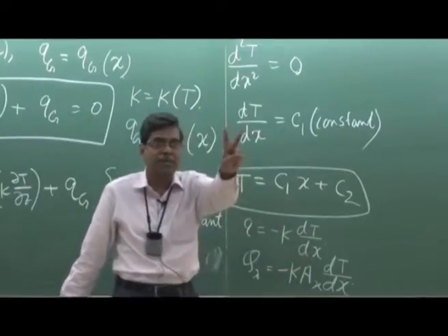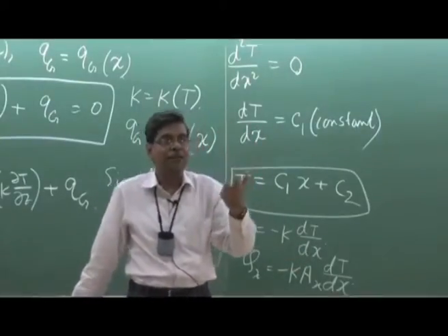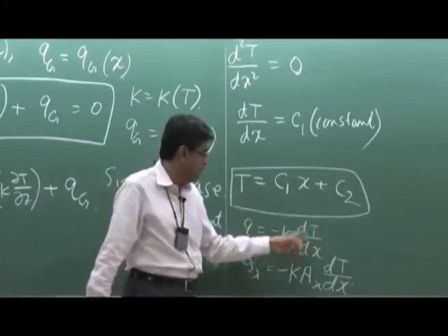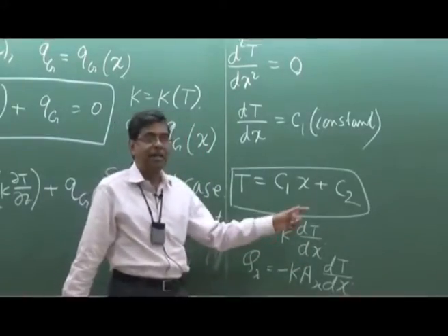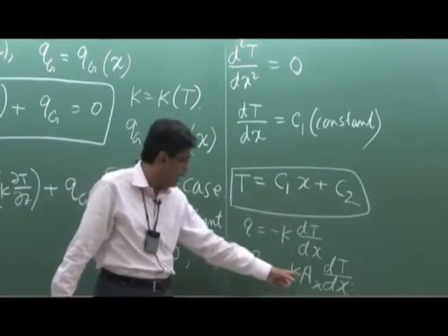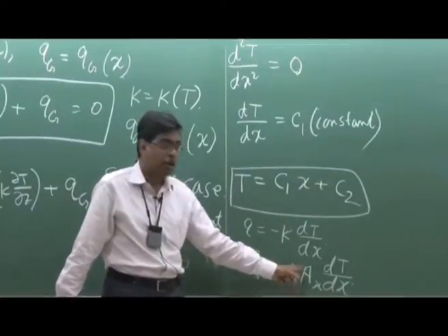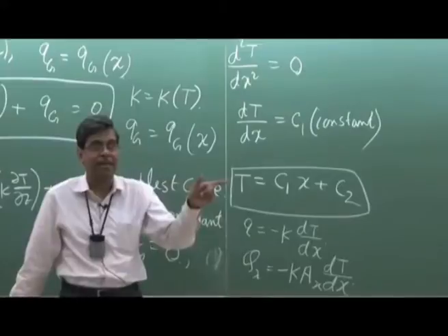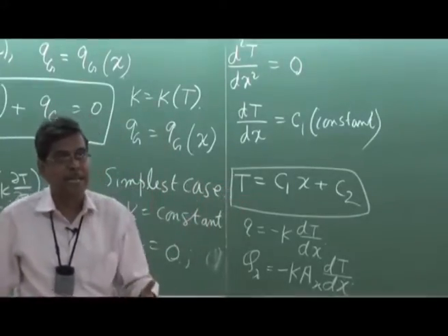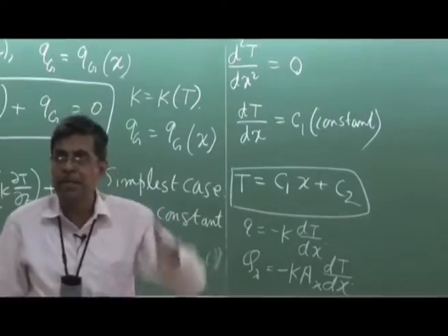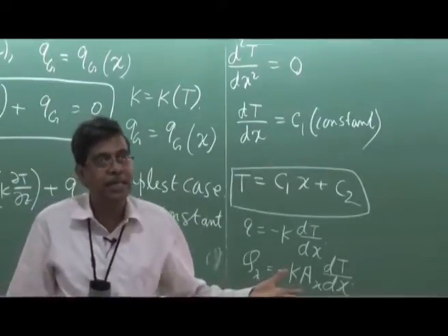If these two pieces of information are there, I will find from common sense that since dT/dx is the temperature gradient, heat is flowing along the x direction. So, therefore, no area will be multiplied here to find the total heat flux, or the total rate of heat transfer across an area A, which is nothing but the area normal to the x direction.